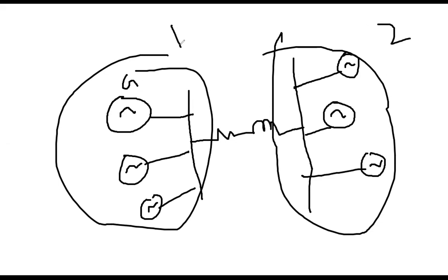But for example, in area 1, one of the generators is facing some issue. Each generator has an automatic voltage regulator, governor, and power system stabilizer. These are primary controllers. Something happened, not properly tuned, or because of little oscillation, that is causing some problem to the whole system. Or it may happen on this side.